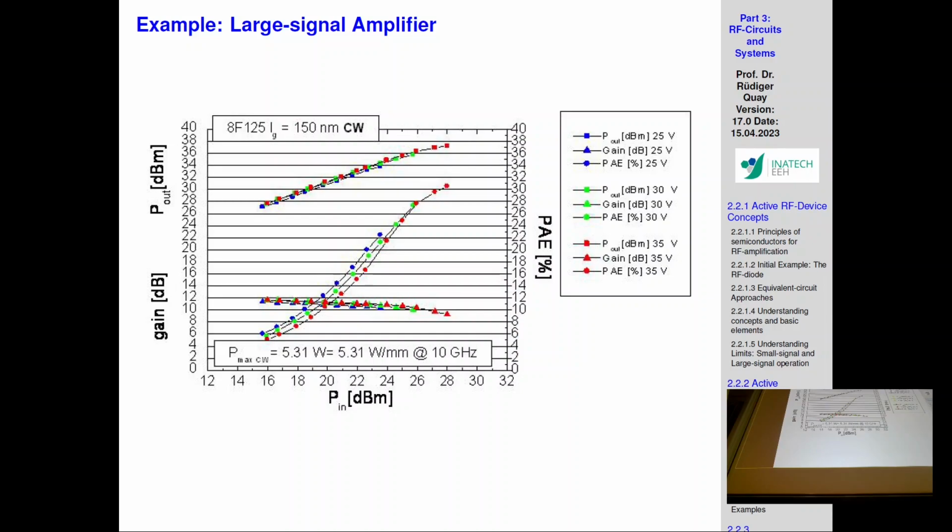At 3 dB compression, where we start to then have this saturation and then the fall, at 1 dB or 3 dB compression depending on how many harmonics we want, and the terminus is harmonics. And we will see that in the next slide. Why harmonics? We designed the amplifier, so we wanted that point over there. We're driving a certain amount of power in, and we have it there. Meaning that for a power device, higher voltage, higher output voltage, higher input drive means a higher efficiency.